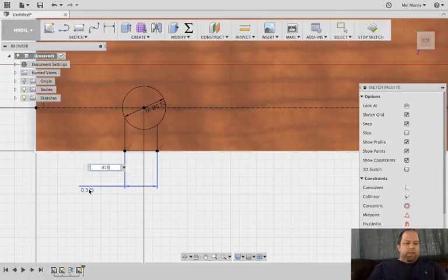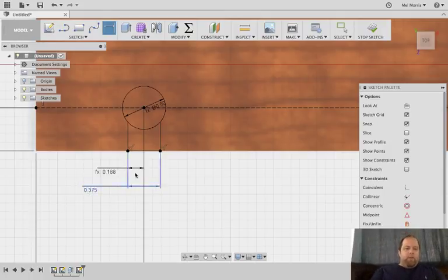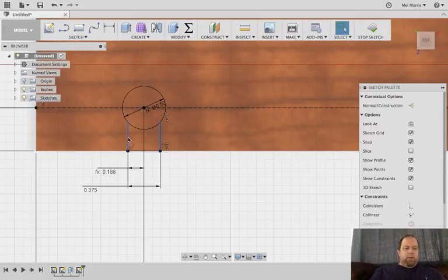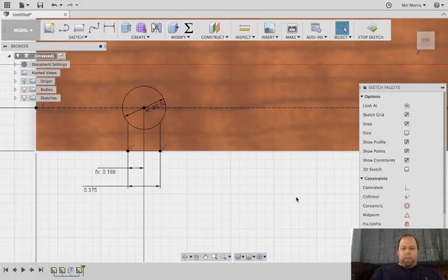So I can make this a formula now. So I highlight this and divide it by 2. Now this centers this opening or slot onto the hole. First we defined this line and then this line, and we can make sure they're parallel. So we can go into our constraints. I want this line to be parallel with that line, and they are.